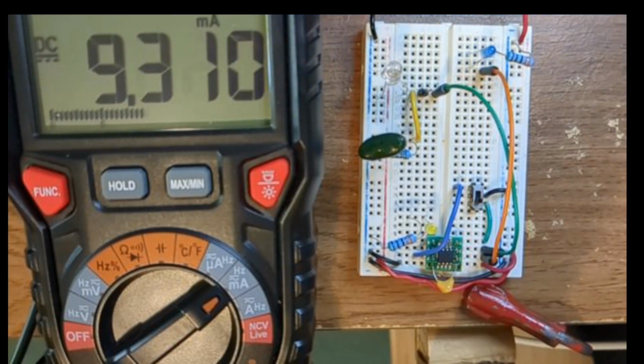So this video is about how that works. What software do you need to initialize the system into this state? And how do hardware blocks on the ATtiny help you achieve it? In particular, there's a hardware block called the Event System, which is used to, in effect, tie other hardware blocks together and allow them to interact with each other even without software interaction other than initialization. And in fact, they can do this even when the core is asleep or in standby state.